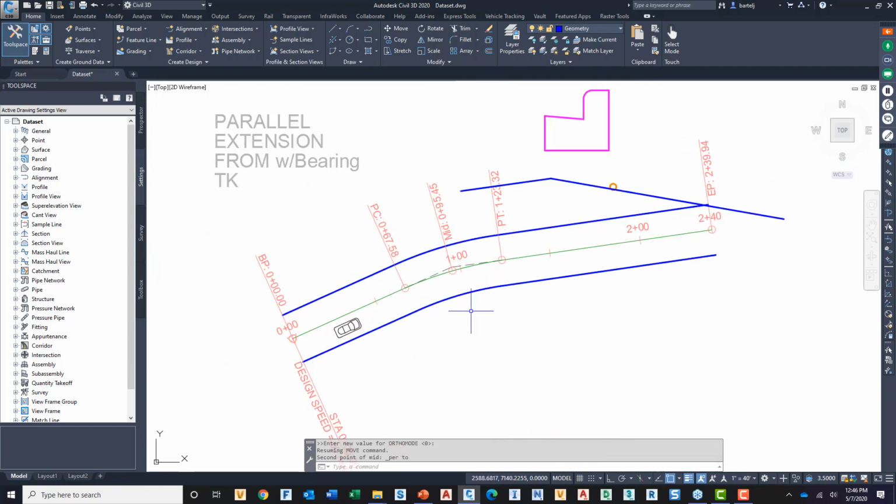In some cases, if I'm going to move geometry to another location, I don't want to go to that location specifically, but to that location plus some additional information, like perhaps when we copy. I'm going to move my circle down here just so it's out of the way. Let's say I'd like to copy this from the endpoint over here, but I'd like it not at the endpoint, but at a bearing and a distance of maybe 20 feet from the endpoint, where I'd like to drop it.